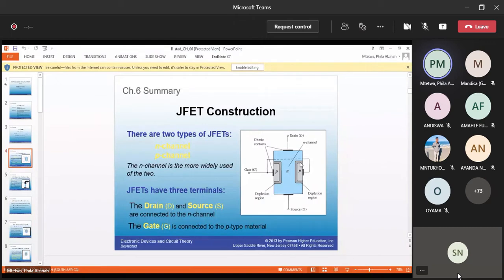So it's important that we have enough of a passage here for the charges to flow, and we control that by the method of biasing. It's a 3-terminal device. That's your gate, that's your source, that's your drain, that's your depletion region, which offers resistance to the flow of current. So we need to keep this minimal, because should it be big, you'll get your channel to be obstructed.